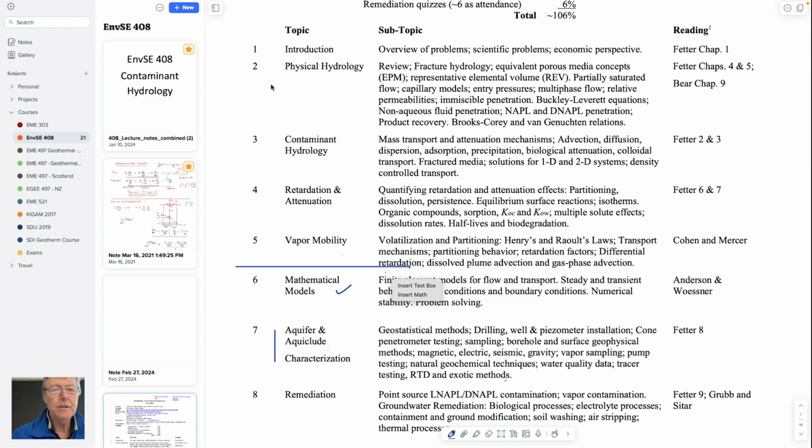We've spent our first little while talking about the role of multi-phase fluid flow in systems. So we dealt with DNAPLs and LNAPLs, talked about them as being the source zones that they get into after maybe a month, and then they stick there, tough to get out because they're held by capillary forces, so they're quite stubborn. They can move, and we understand the behavior of relative permeabilities and multi-phase flow, but largely they will stick there and act as a source.